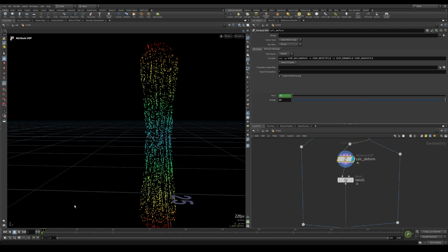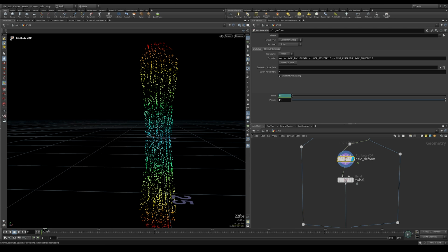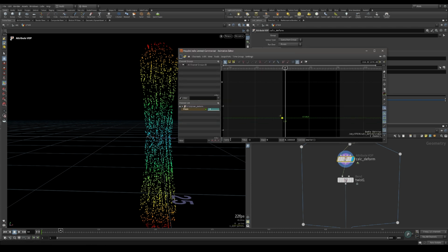So basically we want to start from some negative value, let's say something like -3, and let's put a keyframe on this. And let's say also let's set the FPS. In my case I want 25, so apply FPS. And for the sake of the entire course, let's put the end range to something like 800 and apply. So now I believe we shift click and go on the curve editor. Yeah, it's still on frame 1.